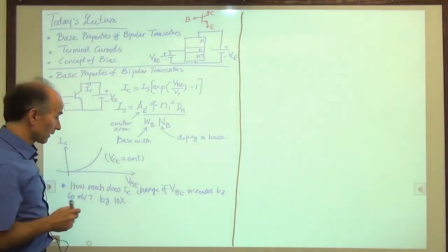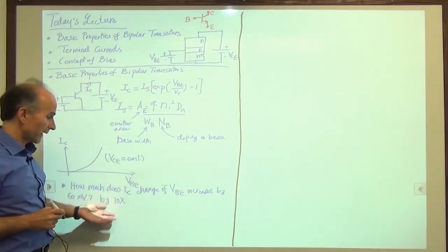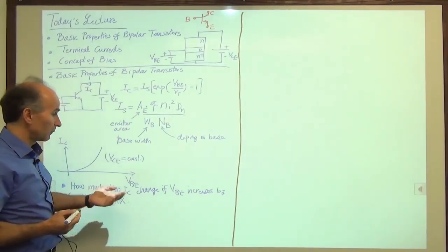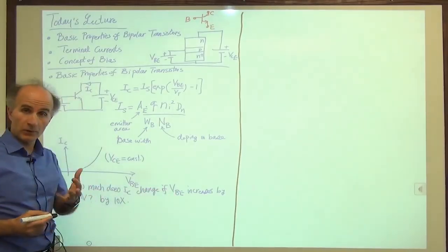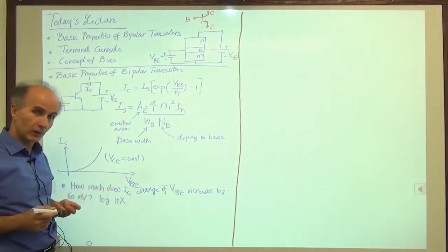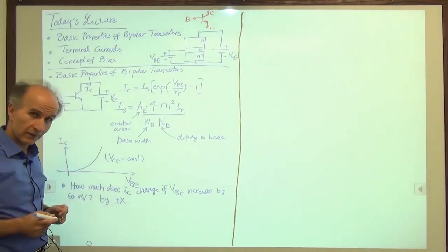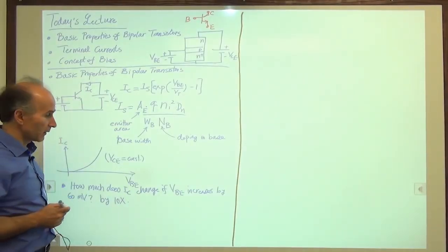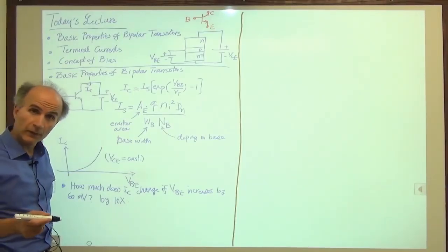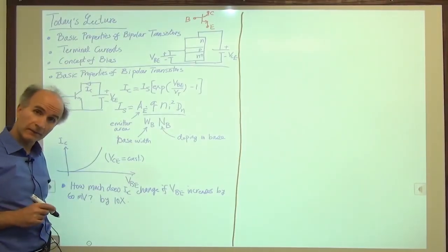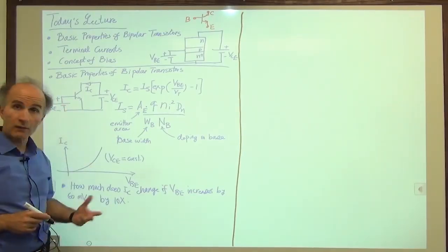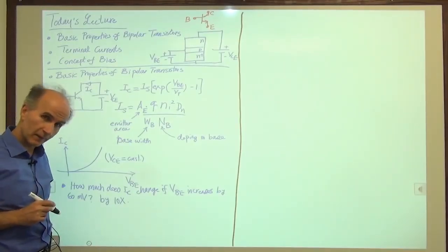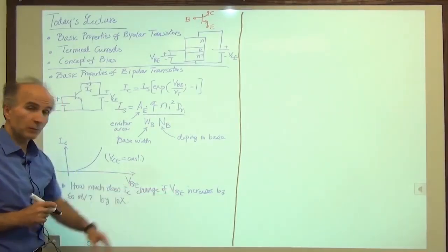That's good to remember, because just like diodes, this tells us that for typical current levels in practice, the base emitter voltage of the device is pretty well known, somewhere in the range of 700 to 800 millivolts for silicon devices. So if you see a silicon bipolar transistor in some circuit and its base emitter voltage is 500 millivolts or 400 millivolts, that would be very surprising. If it is 1 volt, that's also very surprising. Something must not be quite right. So it's always good to remember the range that we would have for VBE.